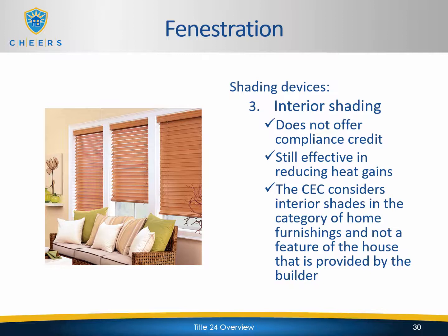Now interior shading, so now we're talking about blinds, shutters, whatever it may be. It doesn't offer compliance credit. It's still effective in reducing heat gains. However, like I said, it doesn't count for Title 24. The CEC considers interior shades in the category of home furnishing and not a feature of the house that is provided by the builder. And because for the most part interior shading can always be moved, removed, changed, and so forth, it's not really a permanent fixture. Therefore, it doesn't give Title 24 compliance.